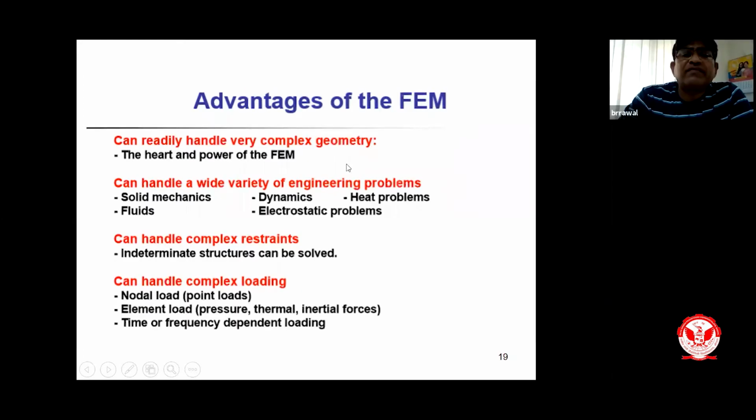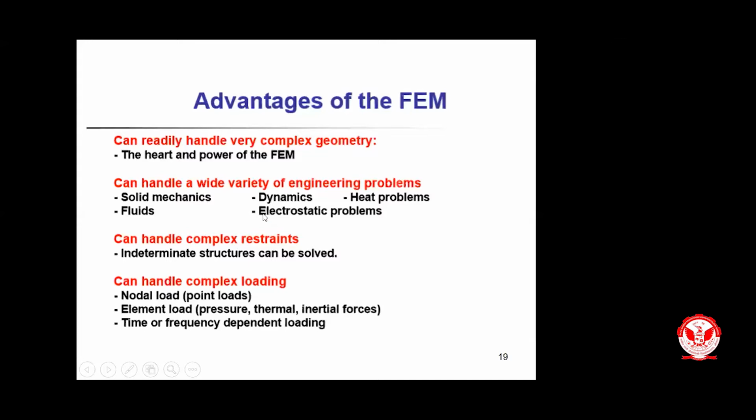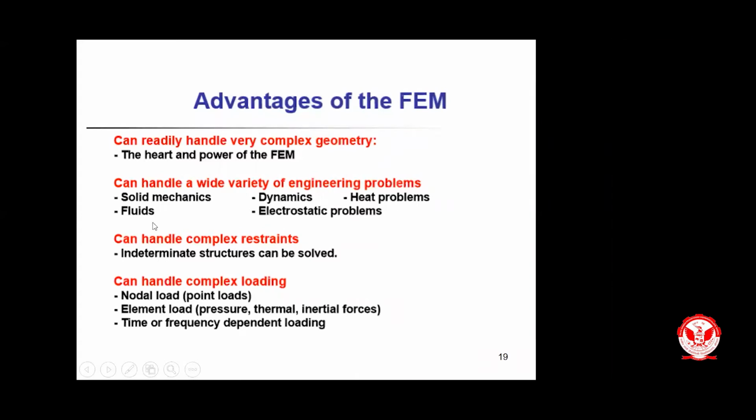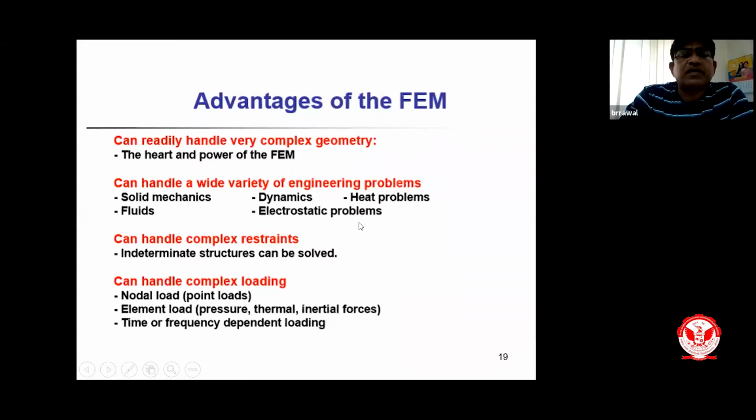Now the advantages of FEM: we can solve very complex geometry easily. We can handle a variety of engineering problems like solid mechanics, dynamics, heat transfer, fluid, and electrostatic problems. It can handle complex restraints, non-linearity in geometry, and non-linearity in material. These are the main advantages. This is an approximate solution, and nowadays it has become a vital tool to analyze engineering problems.